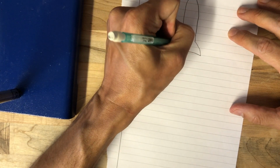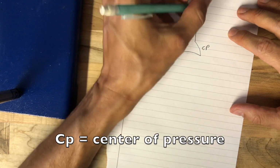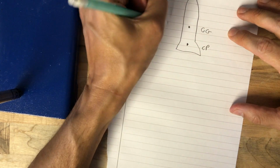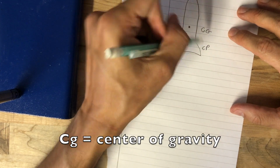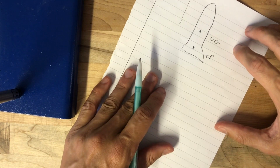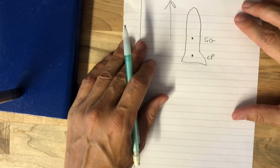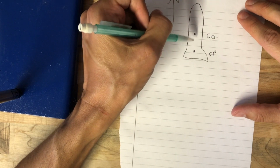So first we know the center of pressure, the point where the air pushes on it, should be behind the center of gravity. So if the rocket's traveling this way, we want the center of pressure behind it. So if it kicks out like this and it's moving up, the wind pressure will push down more on the back end and it'll right itself. So what else would we like?